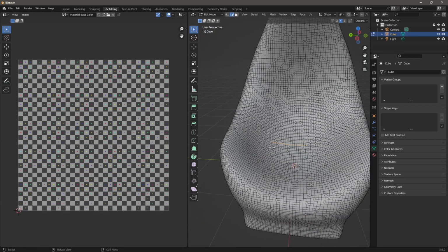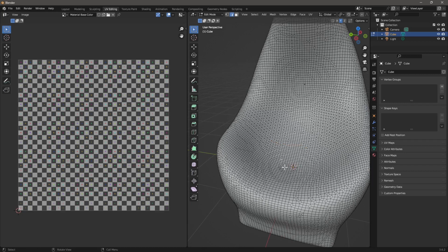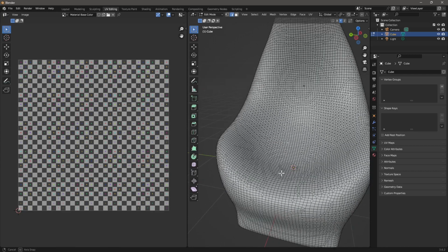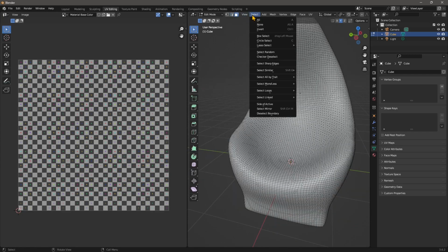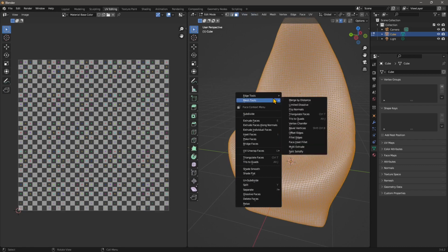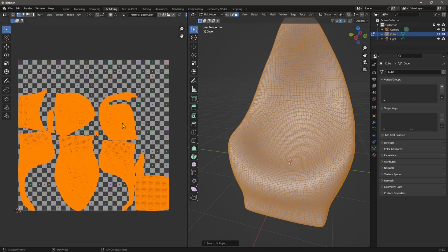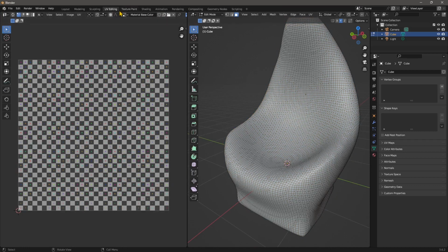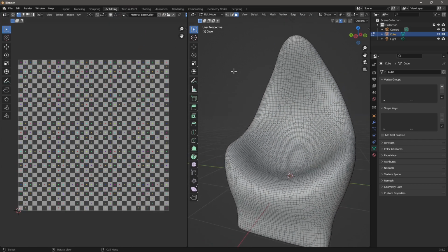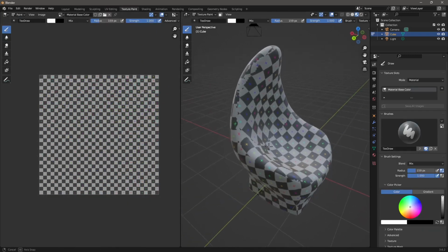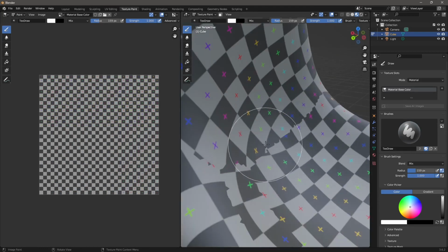If you cannot do that, you can also retopologize. That's another thing you can do, and you can do it with polybuild, but this is in another course and in another lesson, in our video. But we can still work easily with the smart UV project. So I'm going to select all again, right click, and go to Unwrap and Smart UV project. And that's going to work pretty fine as well. We didn't use seams, so when you want to be more precise, when you want to guide your unwrapping, it's better to use seams, but you can see it's still good. And there are some irregular seams right here. You can see it right there.